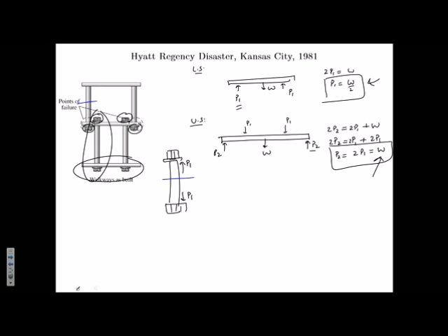Okay? This doesn't even have a factor of safety of 2. And people are going to be walking on the structure. So it doesn't even have a factor of safety of 2, which is completely unheard of. So this is a design problem too then in that sense, right? That it couldn't take a factor of safety. So it's not just the guys who actually put this together who are to be blamed, but even the design guys, because there's practically no factor of safety with this thing.